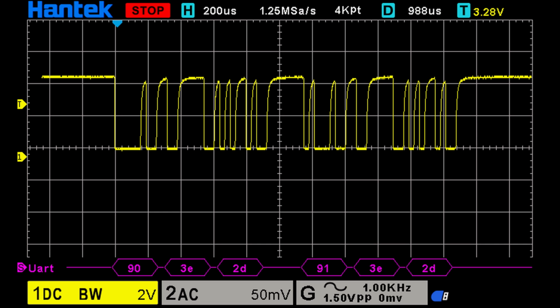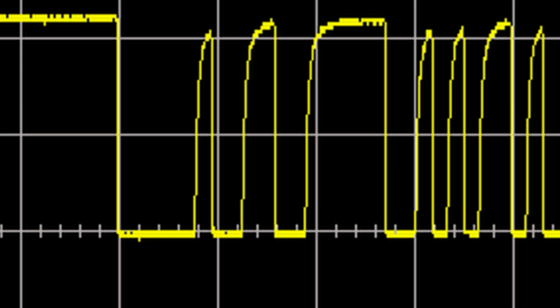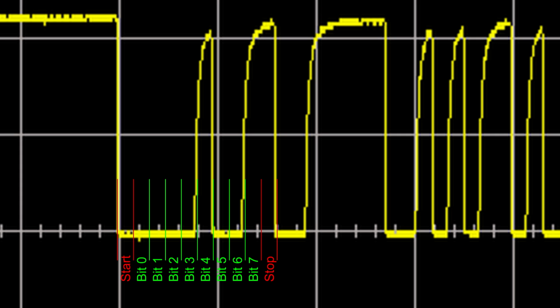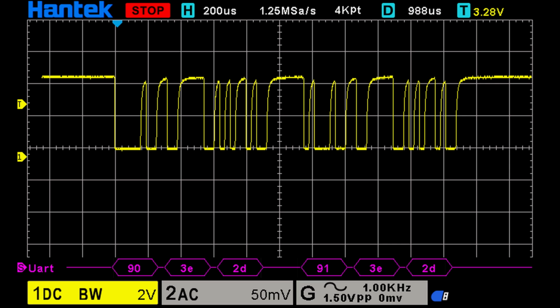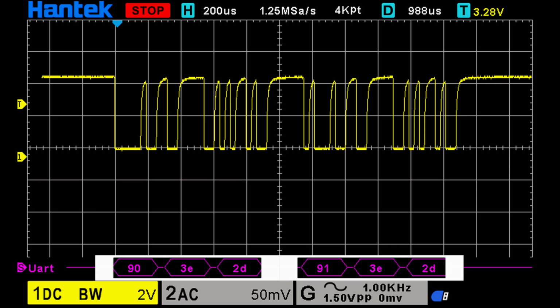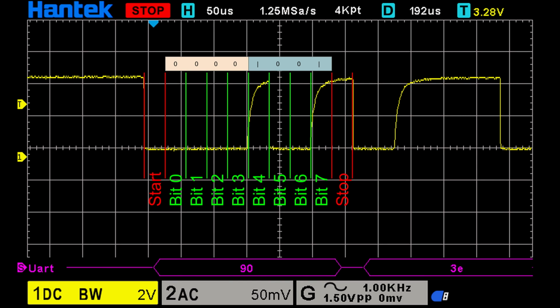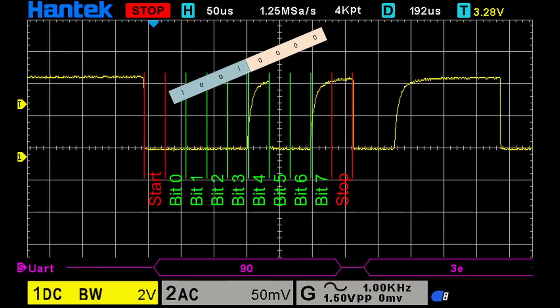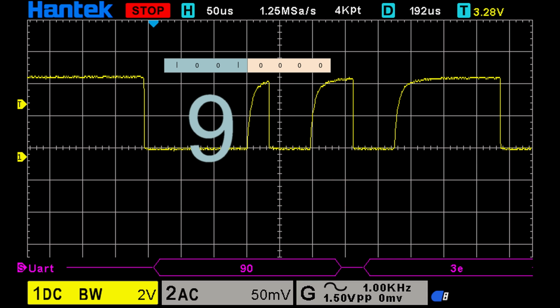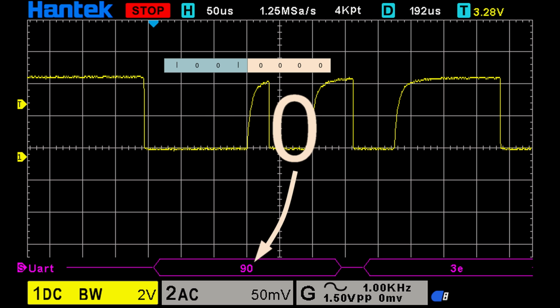Let's look at the message. As we look at the bit stream, note that the least significant bits are being transmitted first. Here, 2 channels, 0 and 1, which represent 2 different voices, are playing at once. The first byte turns on a note in channel 0. The most significant nibble, 9, is the turn note on command. The least significant nibble, 0, is the channel number.